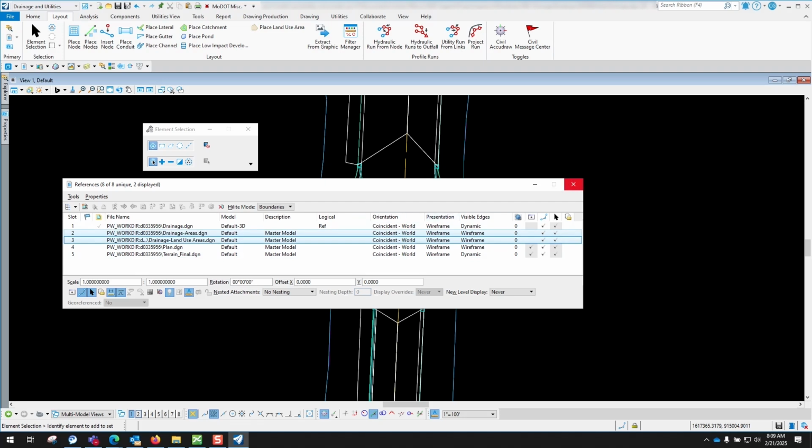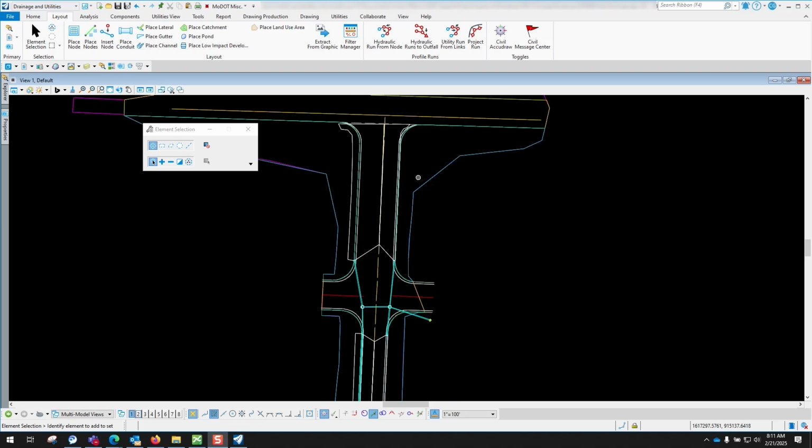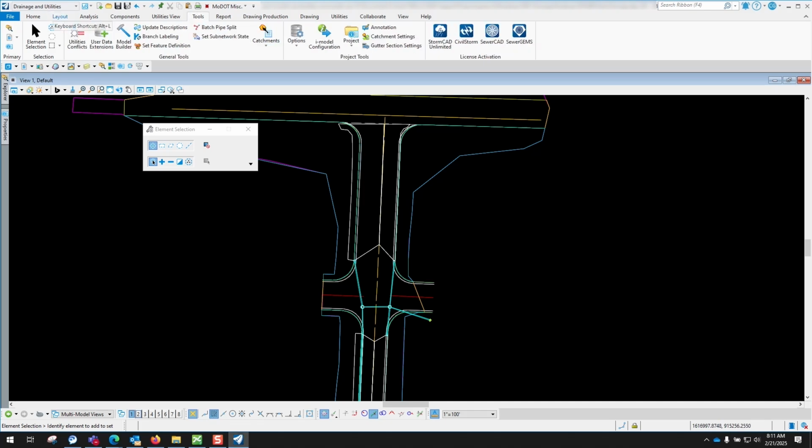Now another option that you have whenever you're creating those drainage areas or your catchment areas is, number one, of course, if you drew in your catchment areas, we could do it just the way we did it right there. Another way that you can try to do it too, you can come into your tools ribbon and go to this option right here that says catchments. And in the catchments, you can come in here and do this delineate catchments.